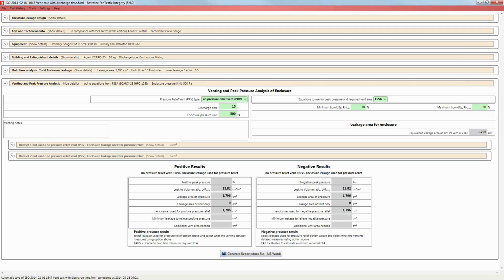A recirculating HVAC is quite different, and it's quite common to have a Liebert-style unit, which is blowing air-conditioned air into the subfloor, blowing back up into the room, and it's circulating around. That will cause continuous mixing. Building HVAC will just cause continuous agent loss, which is quite different from mixing.